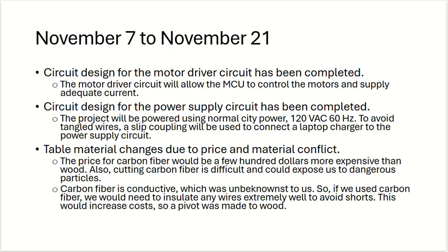Our next research period was between November 7th and November 21st. Circuit design for the motor driver circuit was completed. The motor driver circuit will allow the MCU to control any of the motors and supply an adequate amount of current. The circuit design for the power supply circuit was completed. The project will be powered using normal city power, 120 volt AC, 60 hertz. To avoid any tangled wires, a slip coupling will be used to connect a laptop charger to the power supply circuit.